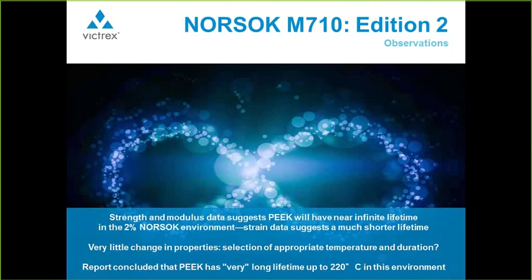So our first observations then, after the completion of this edition 2 test, if I were applying the standard as it's written on paper, I might then write a report which predicts that PEEK has a near infinite lifetime in terms of strength and modulus. Of course, that's something which experience and other experiments tell us isn't possible. I would also conclude that the strain is far more sensitive than strength or modulus to the aging process.